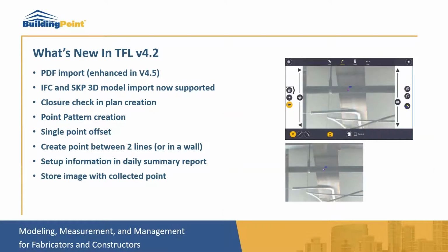And the option to store images with collected points was also made available. Again, here we need an instrument that has vision technology, so an embedded camera, onboard camera with the units. And when you toggle the little camera icon at the bottom of the screen, every time a shot or a point is taken, a picture is also stored at the same time.